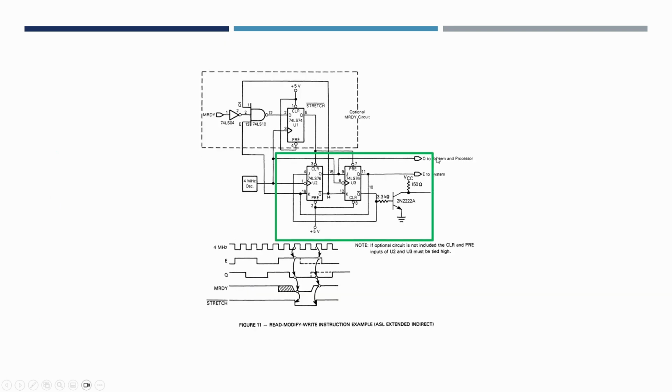So this is the part of the circuit that we did last time. Basically we're feeding our 8 megahertz oscillator into these two flip-flops, and we get an output here, which I think, rather than using a transistor, we used an HC inverter, which provides the higher voltage levels required for the E input signal into the CPU.